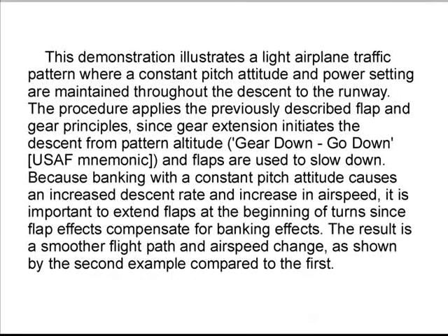Because banking with a constant pitch attitude causes an increased descent rate and increase in airspeed, it is important to extend flaps at the beginning of turns, since flap effects compensate for banking effects. The result is a smoother flight path and airspeed change, as shown by the second example compared to the first.